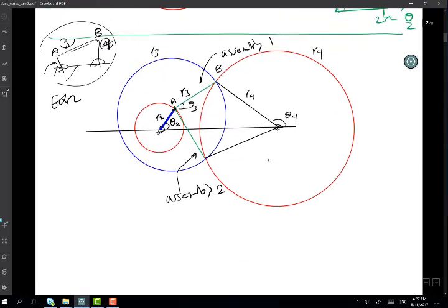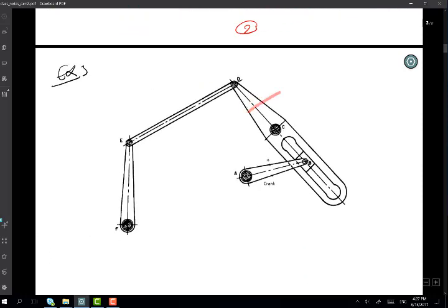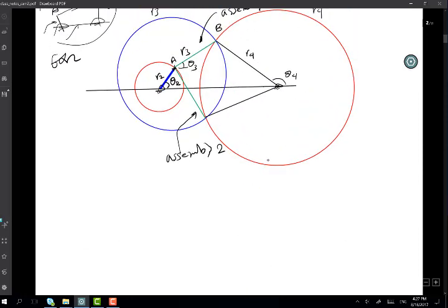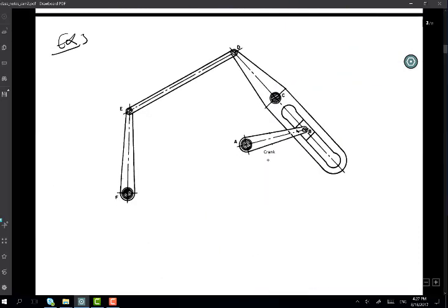Once I know the angle of the crank, because this one link here is like the crank of this 4-body chain, similar to this crank, the blue link, I can find the angle of any other linkage. And to get the angle of this link, I need to work from this end of the linkage.